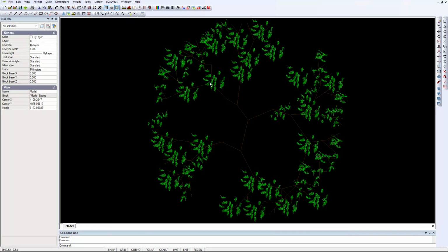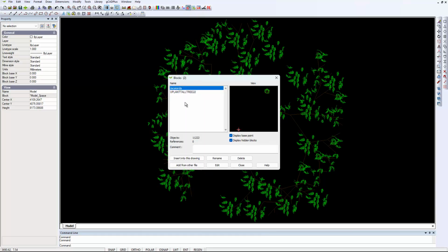Well, let's look a little more closely at the blocks in this drawing, and notice there's our jacaranda, which we have renamed. We need to fix its base point. You remember, you should try and get the base point in the center of the object, but I'm going to leave it there because that's where our original drafter put it, because I want to be able to bring it back into that environment and substitute the drawing that I'm going to finish and clean up for this one.